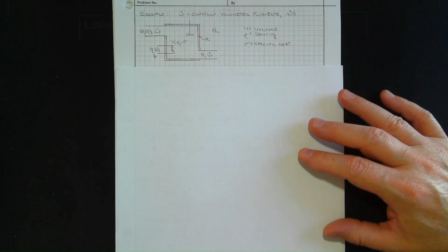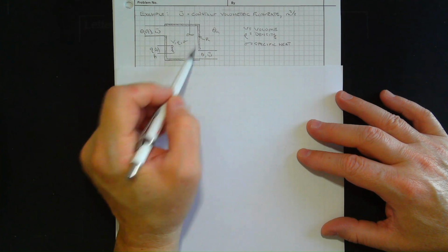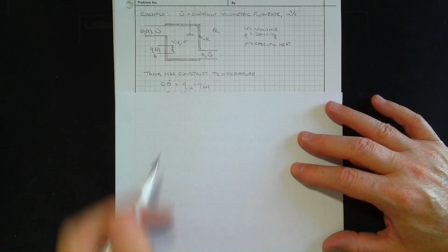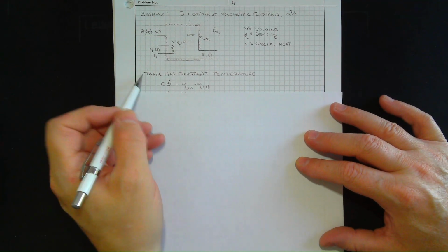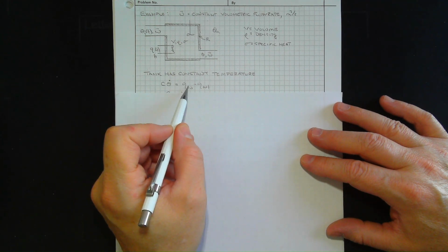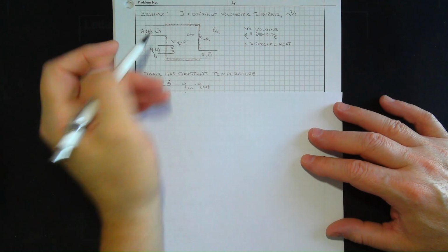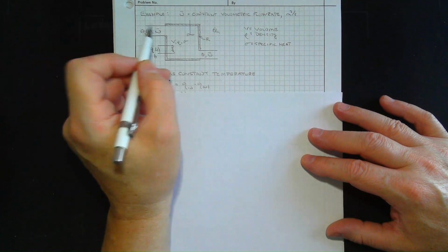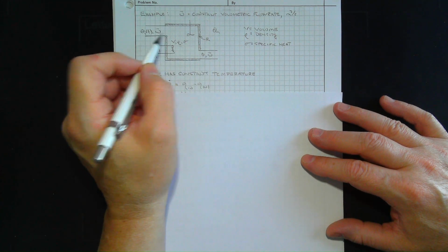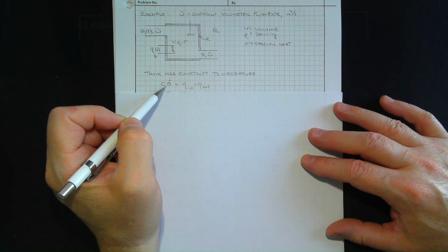Okay, so this is a tank. Heat is being put in and stored here as material comes in, so we're modeling this as a capacitor. So C times theta dot equals heat in minus heat out. Now at steady state, as everything gets to a certain temperature and stuff comes in and goes out at the same temperature, you would expect the temperature in the tank to remain basically constant.